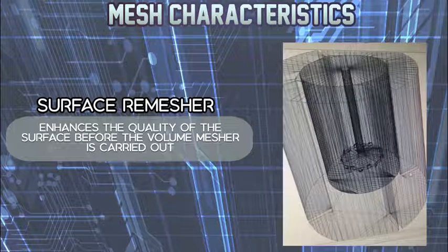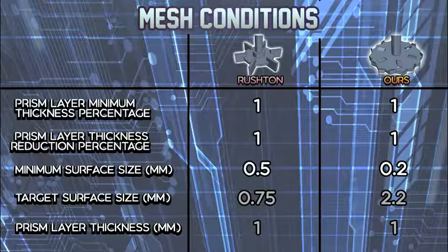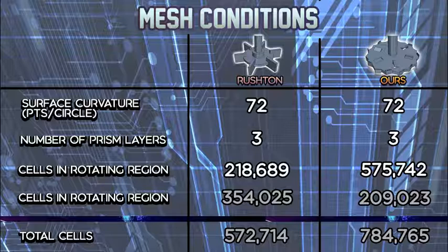This usually occurs in the parts of the geometry that have a steeper gradient, such as the tips of the impeller's vanes, and therefore a finer mesh with more abundant cells is usually necessary to properly and accurately solve the equations. Finally, a mesh with the following conditions was obtained.